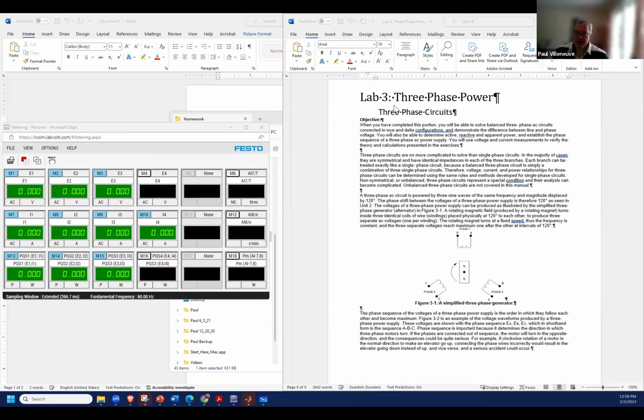So interestingly enough, in a three-phase system, if you have a physical machine, a magnetic machine, and you want to produce a three-phase set of voltages or currents, you actually can just take one north-south magnet here. You can see this is the magnetic material, and it doesn't care about the rotation. It's just that as this passes phase one, you're going to get a peak value and a negative peak as the north and the south change.